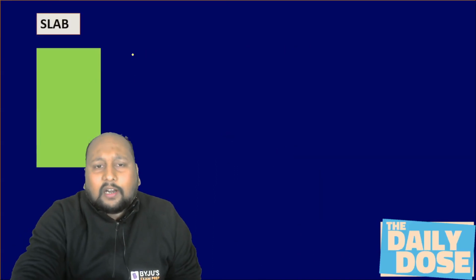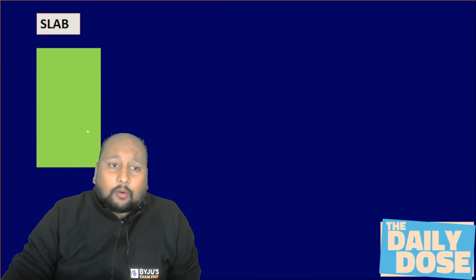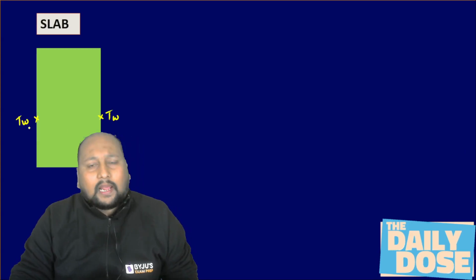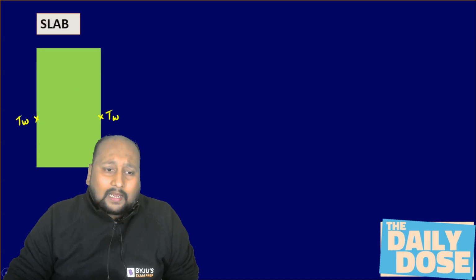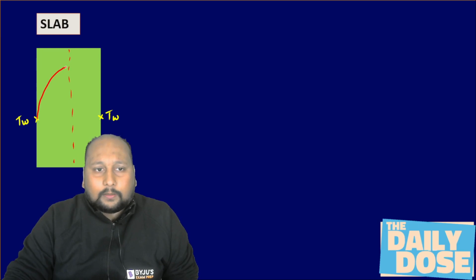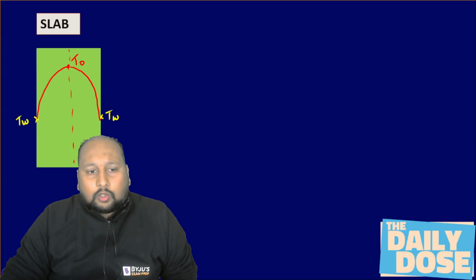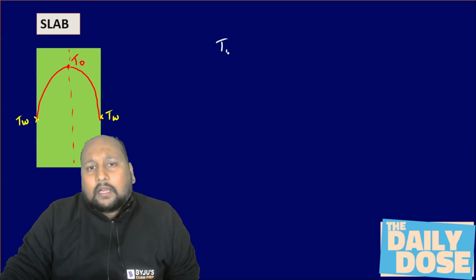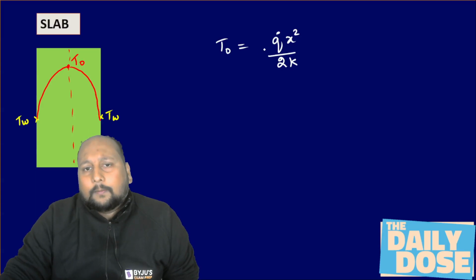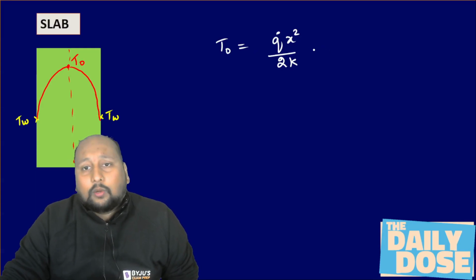But if I talk about a slab, and that too the case where both surfaces have the same temperature, we know that the maximum temperature will lie at the center line and we will have a parabolic profile. And if I assume the maximum temperature as T naught, we can simply say that T naught is equal to q dot x square by 2k plus T.